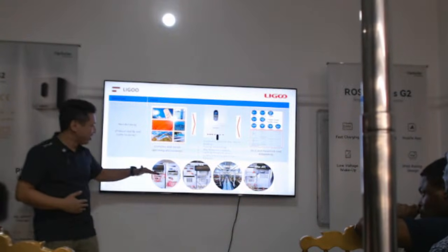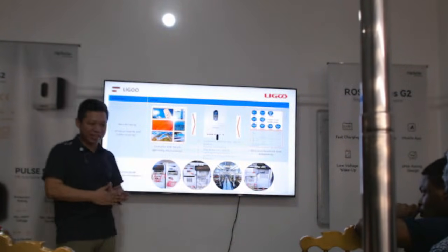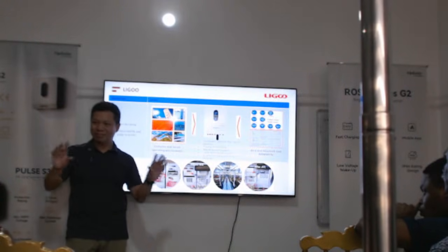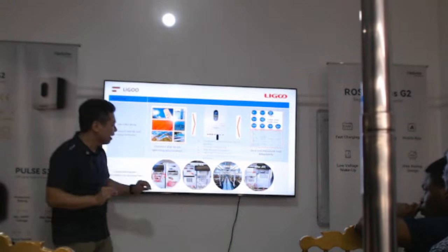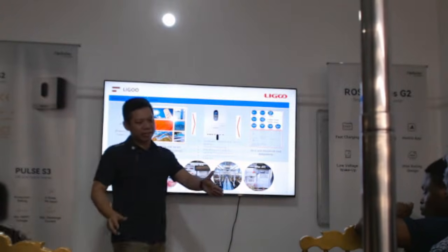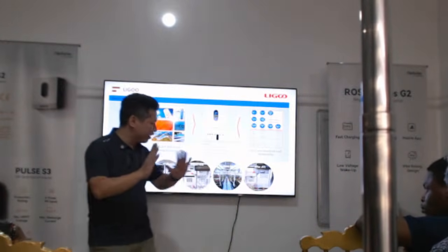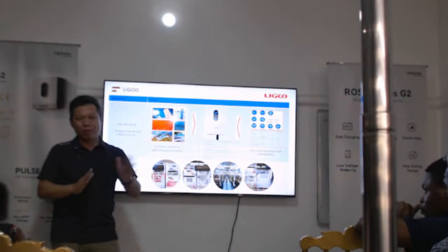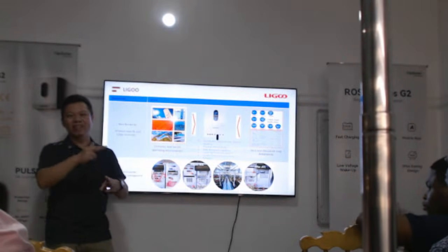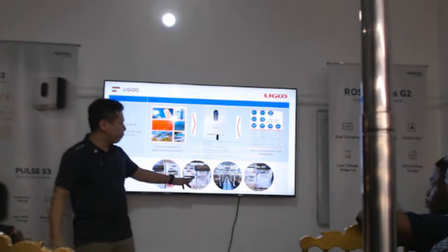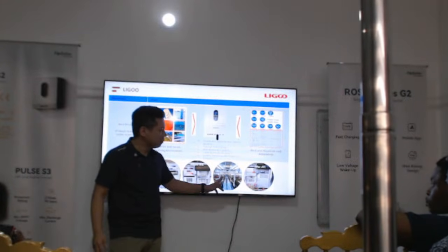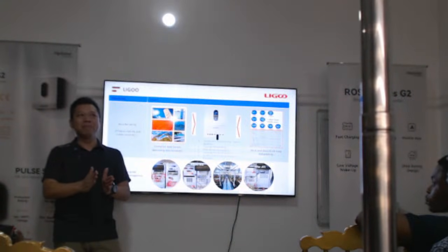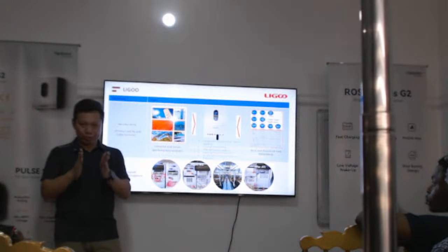Okay, the problem. This is the FCT, which tests the product PCBA. We have to do many tests to make sure the PCBA is okay. Another point, we assemble this product and do an automatic test, checking the unit performance and safety. We also put the sample in the burn-in room at high temperature, 100%. We do the test.